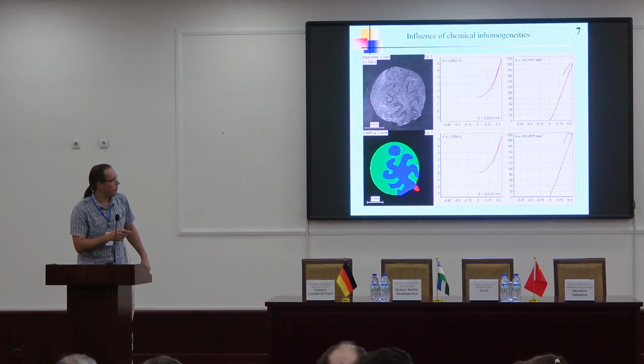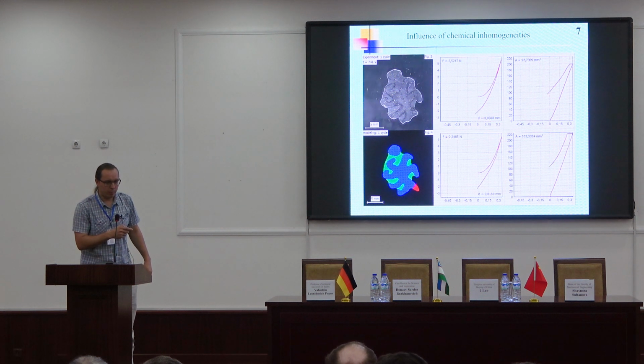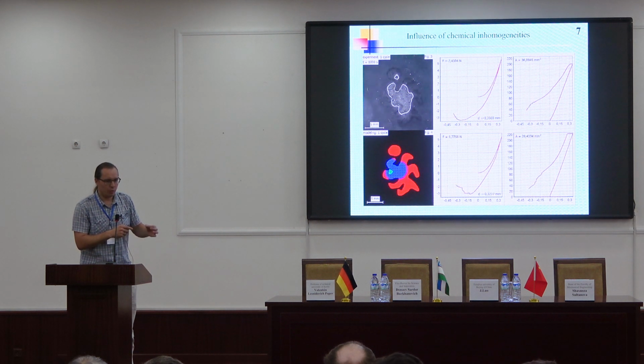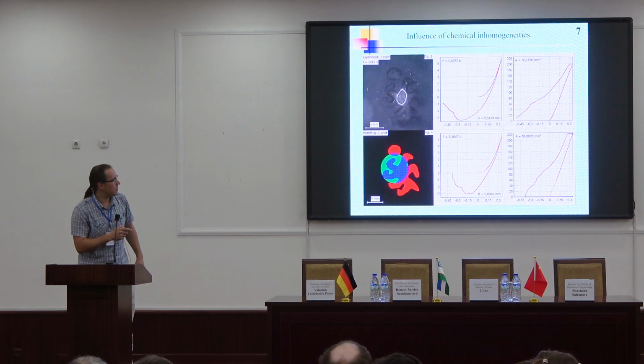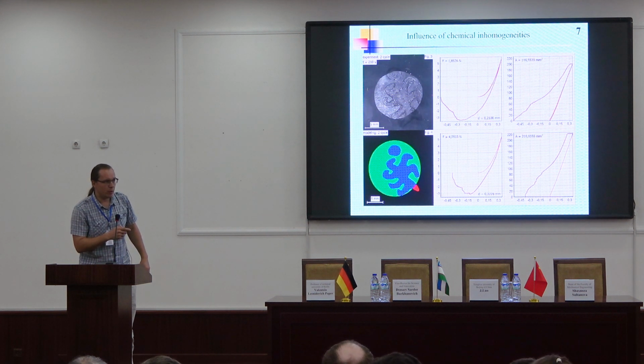It's a chemical treatment, and after this treatment we observed an increase of surface energy up to 20 times. It's also a spherical indenter. In the usual case with homogeneous properties you have a circular form of the contact, but now it's something different. And in simulation with the boundary elements method, we got the same results.